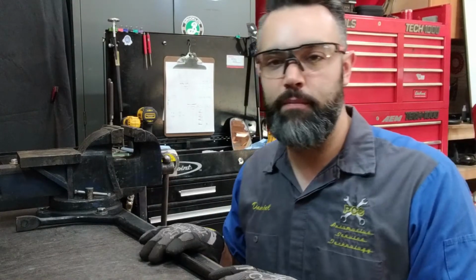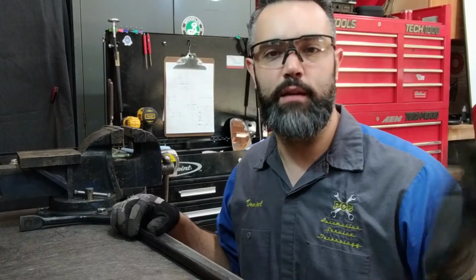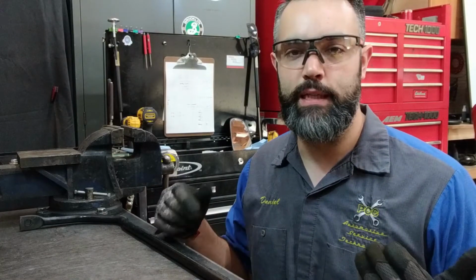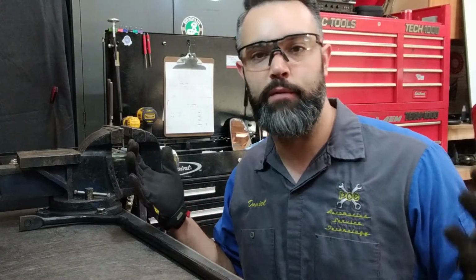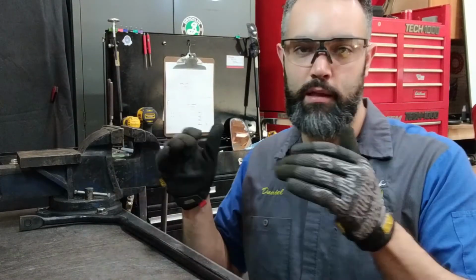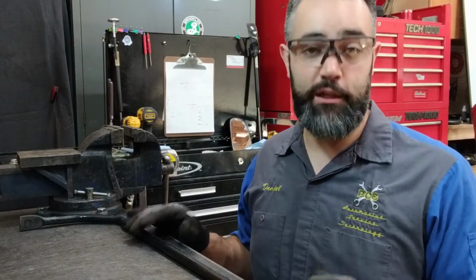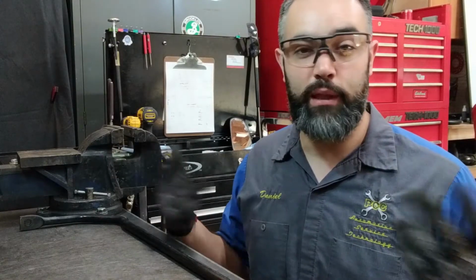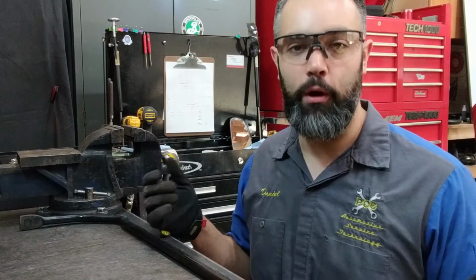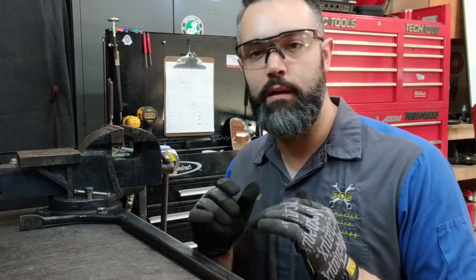What that can do on some vehicles, let's use the electronic example, the hydraulic example is not as common as the electronic. The same thing can be accomplished through hydraulic pressure from the power steering system, since there's about 1200 psi worth of pressure able to be utilized for function, whether it's for the hydro boost, the power steering, or in some cases, the active sway bar control. Electronic motors can do the same thing with fewer fluid lines, less potential for leaks, and overall less weight of the vehicle to simplify it a little bit more. So electronic motors are bridging that gap of where hydraulic functions used to be for some manufacturers.